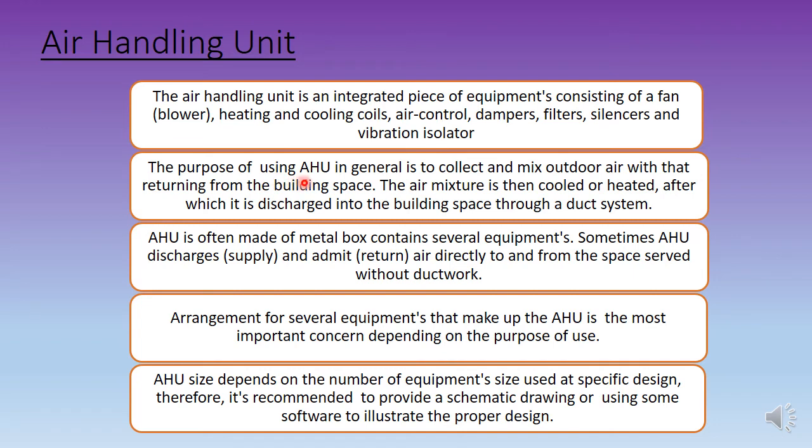The purpose of the AHU is to collect the mixed outdoor air with the return air from the building space, and then it will be reconditioned. It will be filtered, cooled or heated, after which it is discharged into the building space through a duct system.